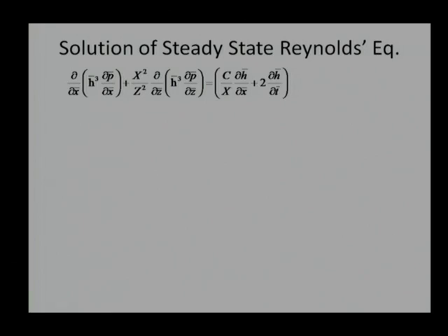That is why I am emphasizing that you understand the system first, understand the dimensions first, and then think which numerical analysis should be applied. If time does not matter much, you can go ahead, but if time matters to us, then we should think of a solution based on dimensions. Now, there is one modified version also. We say that we are assuming a steady state Reynolds equation. Plates are not going to change position with respect to time. Inclination remains the same, film thickness remains the same with respect to time.